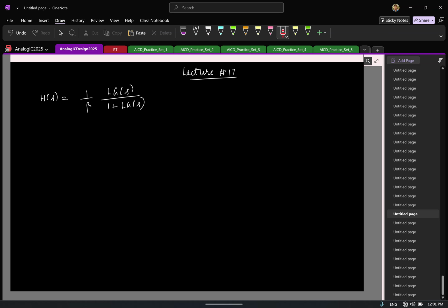Now, if I give a transfer function, what is the check you will make to see if it is stable or unstable? Poles should be where? Left half of the s plane. So of course, if it's a first order system, we directly substituted the loop gain. It was easy to do. Maybe for a second order system, you can calculate. Third order system, again, it will just go out of our hands, right?